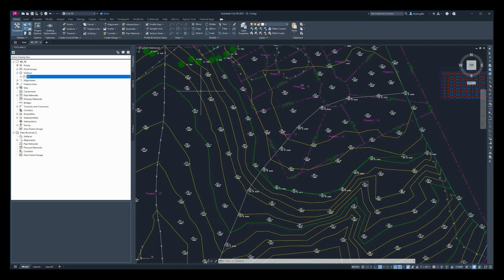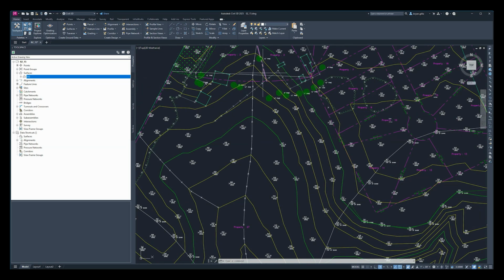And let's go ahead and go back to this second polyline we created. We can click on it, or really it's the only polyline, the other one's a feature line. We can click on it and we see we have kind of three grips here. Now if we grab this middle grip, we get options to stretch, add vertex, or convert to arcs. So let's go ahead and hover over that, and we're going to hit convert to arc.